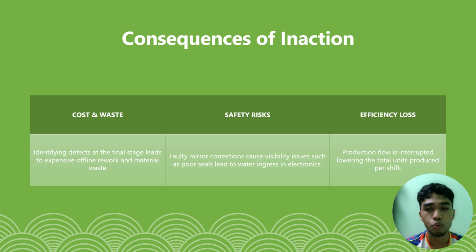The check sheet was used to record the date, defect type, defect position, and countermeasure taken. Some examples include side mirror cable not fully clipped, which is more concerning, some from wrong installation of the handle, and some where the door is unable to lock.